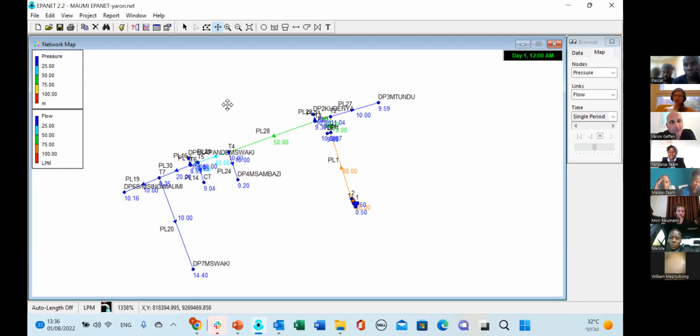I can tell you what our requirement is, and we're going to have it in the water manual. The new version is coming out really soon. Hopefully next week you're all going to get the new version, and I think we're going to put in a step-by-step EPANET design so the contractor can have it with them. What we usually do in other countries is take the sustainable yield from the pumping test and divide it by all the taps. If you see that the total demand in the whole system is the same as the sustainable yield, then you know that it's fine. You won't know exactly what the flow will be in each tap.